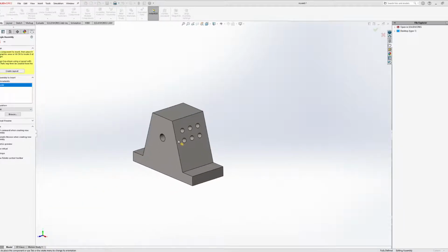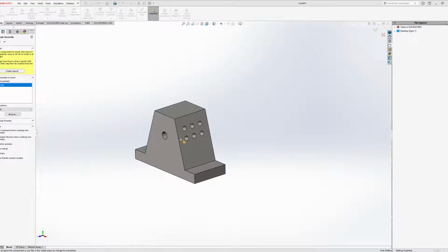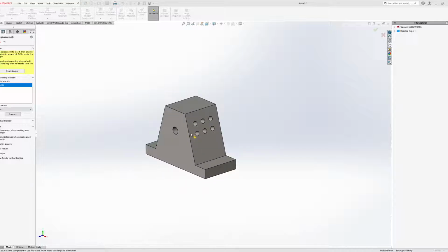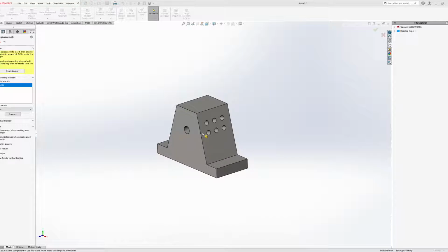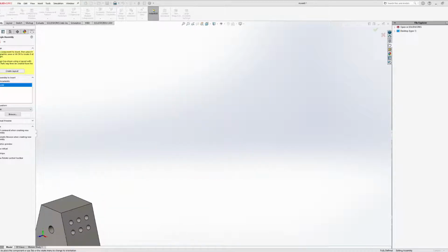You might have to squint a little bit if you're looking at my stream, but if you do have SolidWorks open, those buttons are going to represent what axis it will rotate around. So currently it's saying I want to do a 90-degree rotation about either the x-axis, the y-axis, or the z-axis.